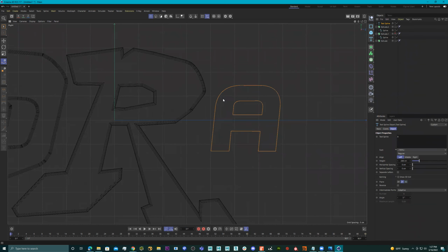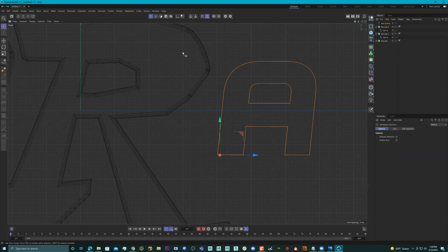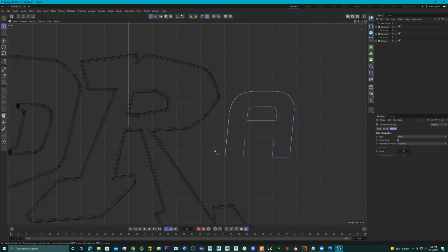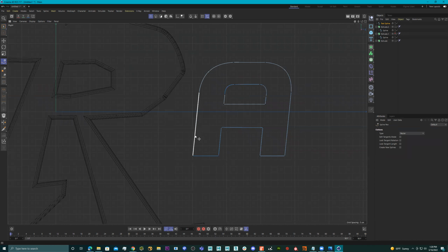And now I'm gonna modify this. So here's our spline. And I'm just gonna go to this selection right here. Let's see how many points are on here first. It's not letting me modify. That doesn't seem right. If I press C to make it editable, that's what it is. I had to press C to make it editable. All right, so now that I've done that, I can go over here and probably add a point if I need to. Yep, cool.